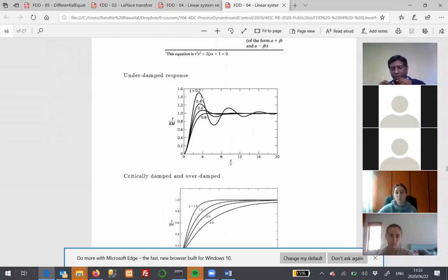So for instance, if you have a small temperature difference, but your Kp value is very high, then that system might be dumping lots of steam into your reactor, into the jacket at least. So the stronger the Kp, the stronger the control action. And you can imagine if this is temperature, a strong control action will cause you to shoot up very rapidly here. And then the moment the temperature goes over the set point, it's going to be a strong negative influence, so it's going to jump down here. So you see, the stronger your control action, the stronger will be your oscillation as well before the system settles down to a steady state.